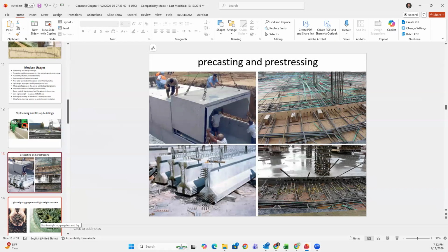Yeah. If you make a cylinder of concrete and you go stand on it, nothing happens to the concrete. Concrete is good in compression. But if you get the concrete and start to pull it, the aggregates come apart. The glue comes apart. The strength of the concrete is in compression. Where the concrete is weak is tension. That's why you put rebar and you tension the rebar to induce tension strength into concrete. Am I clear?